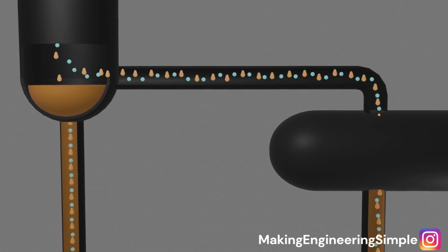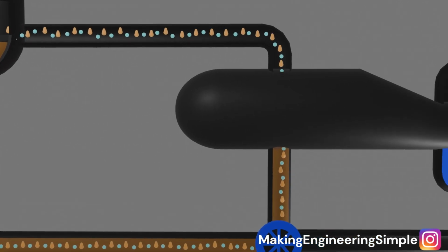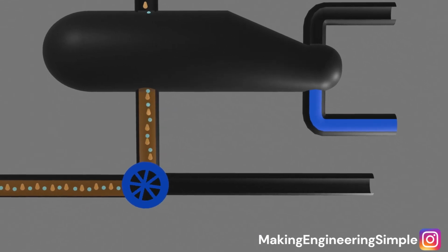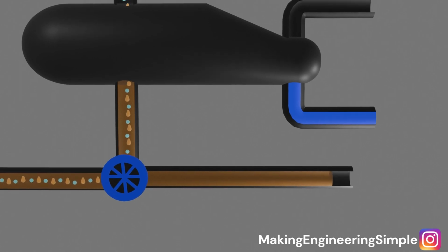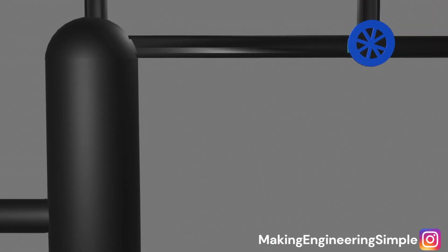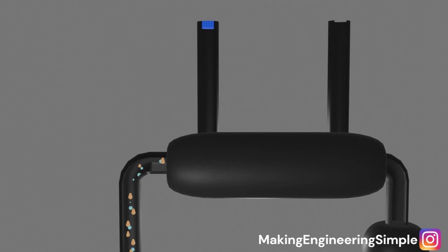Meanwhile, the liquid that doesn't vaporize continues to be monitored. If it meets the required chemical specifications, it is officially drawn out of the system as our heavy bottom product. Meanwhile, the lightest components that successfully boiled all the way to the top of the column exit as a hot vapor. This vapor passes through a condenser, typically a shell and tube heat exchanger.